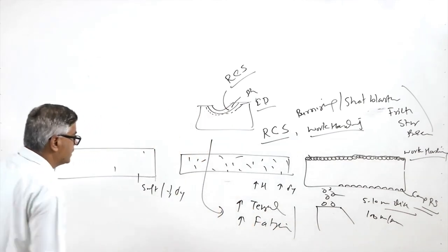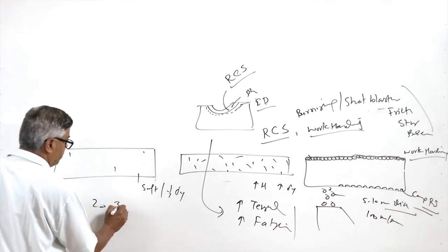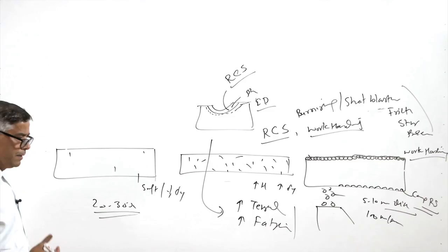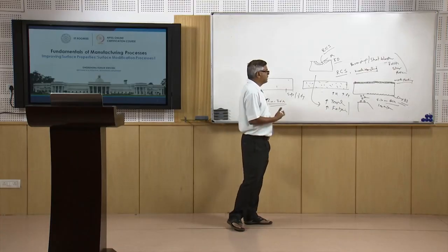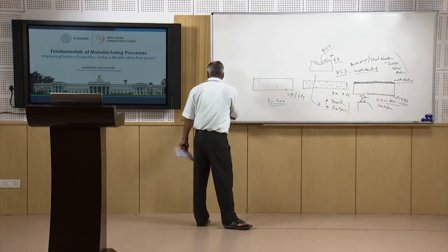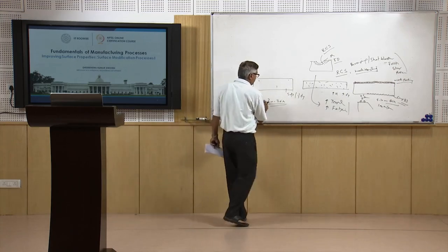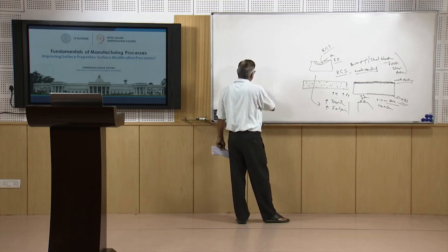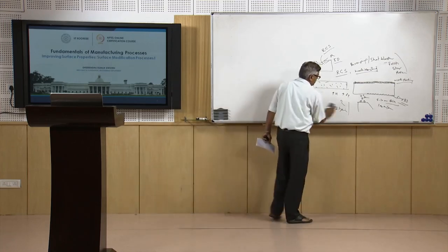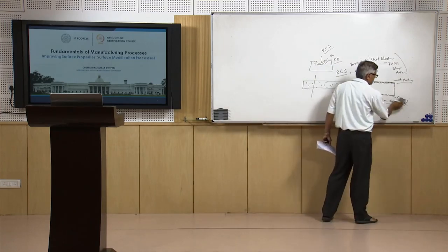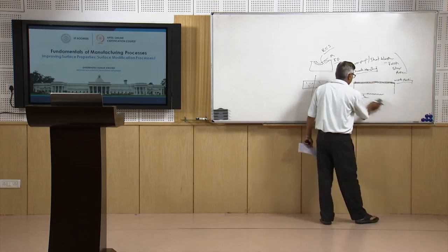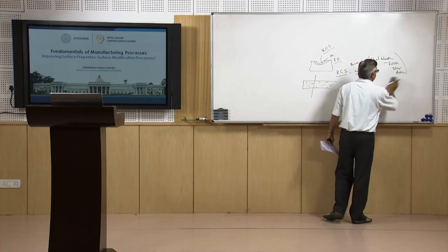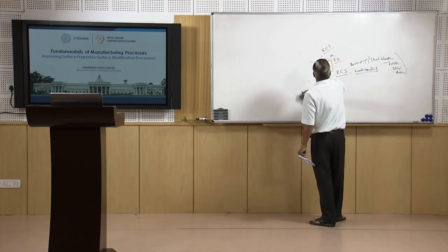It has been reported that a 20 to 30% improvement in fatigue life can be achieved through mechanical working based methods in a very controlled way, so that the surface layers are deformed plastically in a controlled way, residual compressive stresses are developed, and the surface gets hardened and strengthened, which in turn resists plastic deformation, and the nucleation and growth of the crack required for fatigue failure of the component.